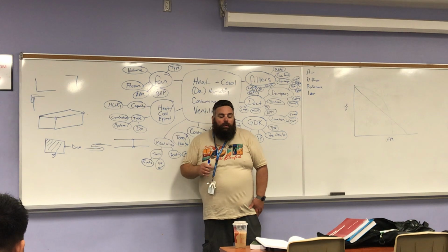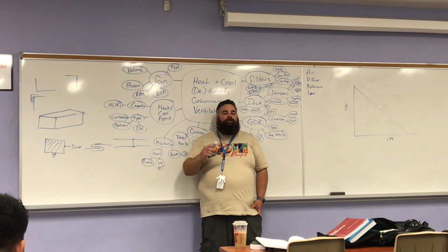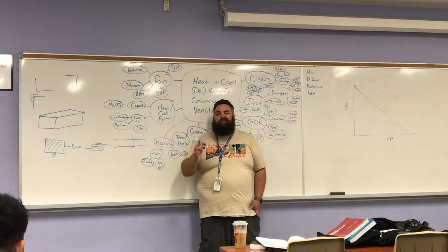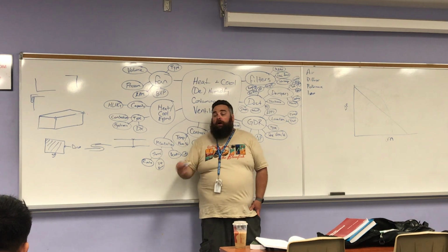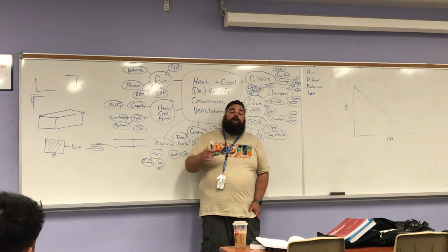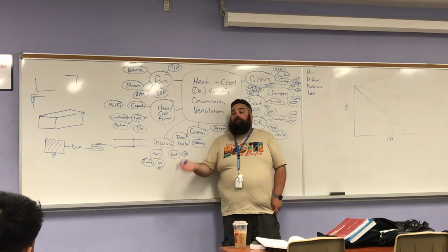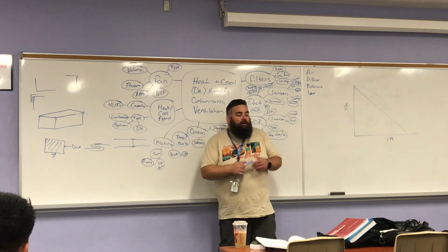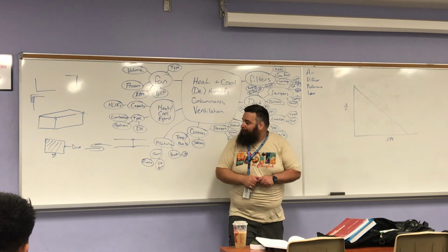Where we might do acoustic lining the whole way is if there are sound critical environments like perhaps museums or recording studios, libraries. Even still, I don't think we're going to acoustically line the whole library, but there might be parts where we want to do that. We have to take that into account and design around it, because now I have a very different friction factor than what my duct says. Okay, that's more of an extreme case. For all intents and purposes, we're only going to acoustically line the first 10 feet. Okay?